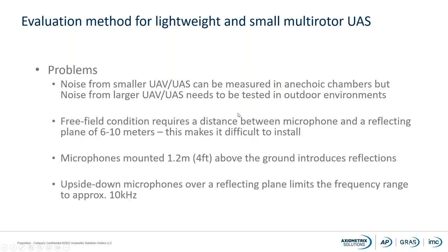So the problems we are facing are that we can do some measurements in anechoic chambers, but noise from the larger UAVs needs to be tested in outdoor environment. What we have said is that free field conditions require a distance between the microphone and the reflecting plane of 6 to 10 meters. This makes it difficult to install and costly.